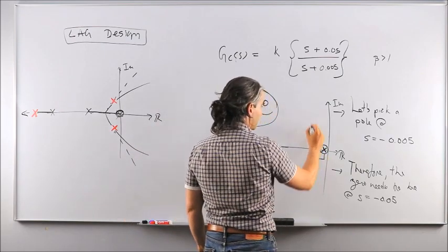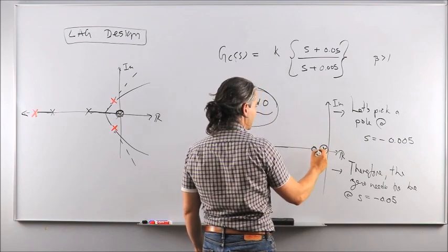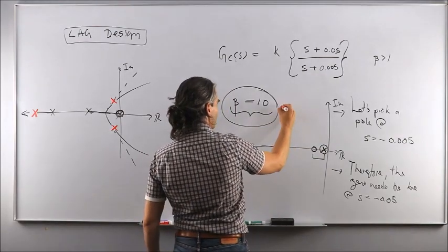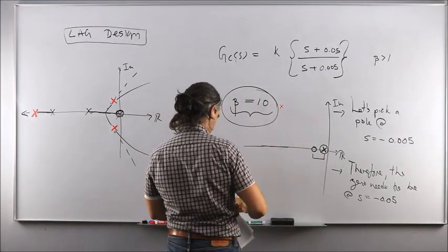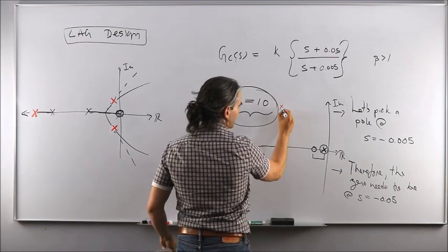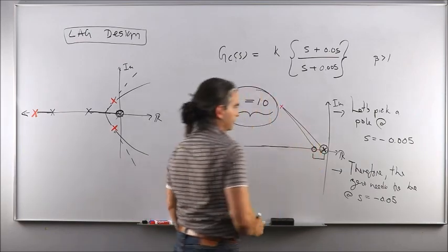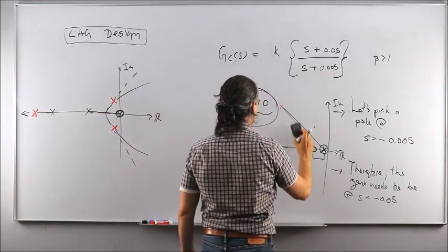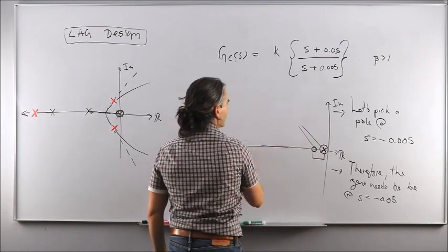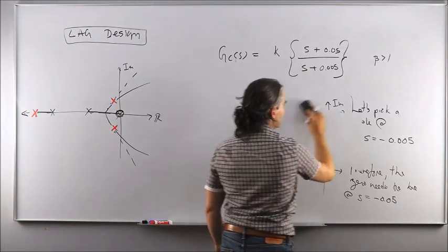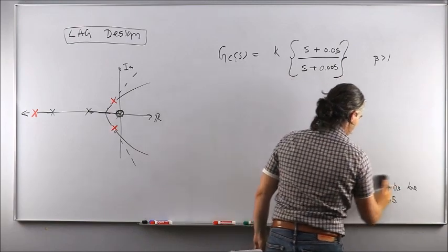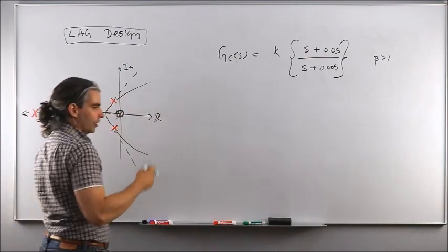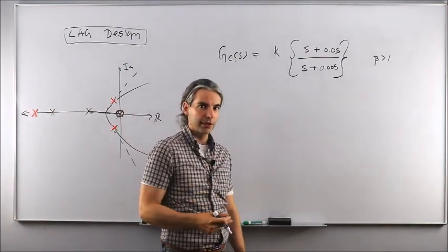The phase of a 0 is a positive phase minus the phase provided by the pole onto the desired pole location, which would be way out there on this scale here. So this angle compared to that angle, this is pretty much the same thing, negligible. So you don't need to worry about that, because the root locus was already going through the desired pole locations. Or in other words, the phase of the root locus evaluated at the pole location was already minus 180 degrees.